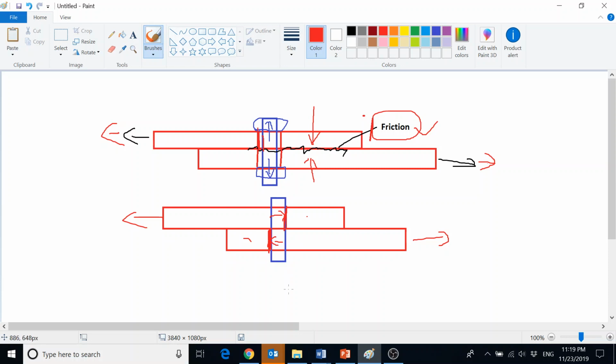So this is called a bearing type connection because the bolt itself does not have enough pretension to create the friction needed, like in this case. So this one can be what I call snug tight, but the high strength post-tensioned or pretensioned bolt has to be installed with a torque wrench or a special installation device to make sure that the bolt is pretensioned to the needed tension force.